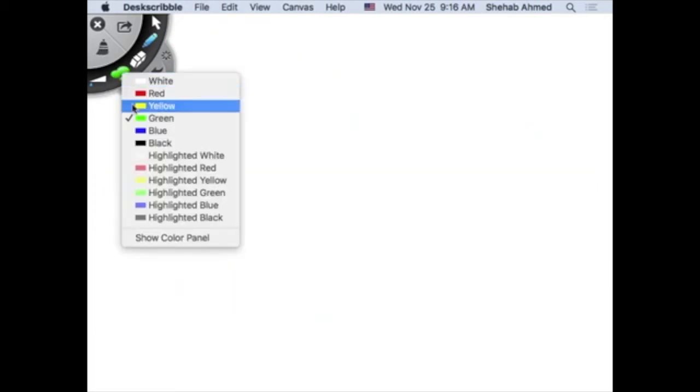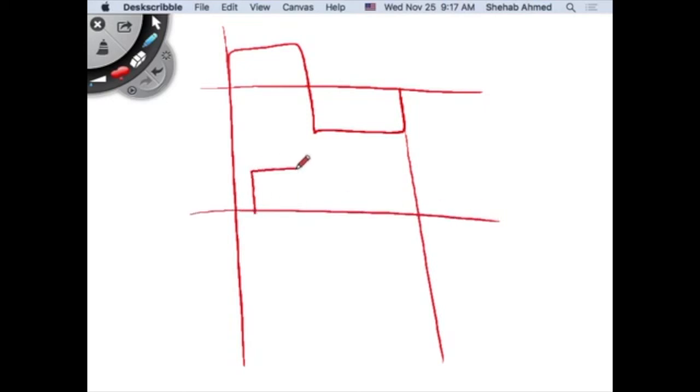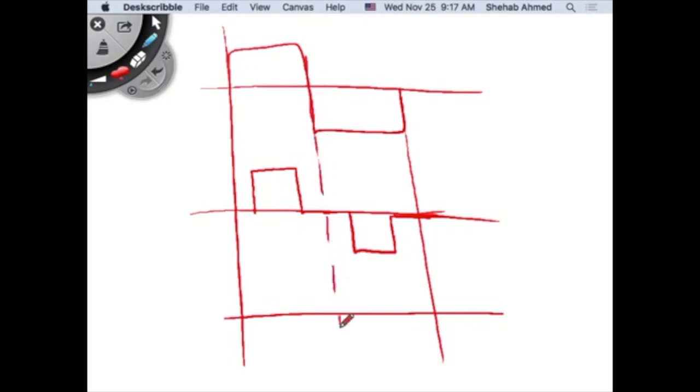We will look at the equations for all this, but they started with this, then added zeros. Then they realized that this is a nice trick to play with. If I add some zeros here and control my pulse width, it's interesting, I can get better harmonic content. Fine, I have to raise this value of voltage, right? Because if I want to meet the same RMS value, I will have to, of course, raise this. But they found a nice trick.